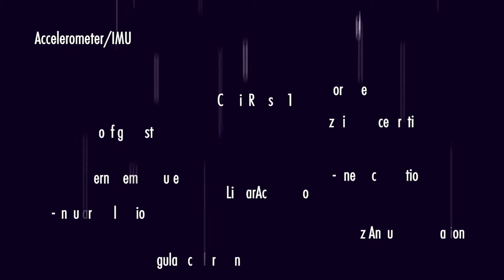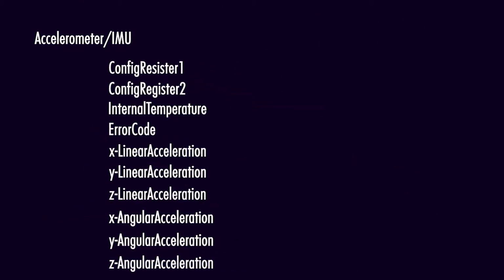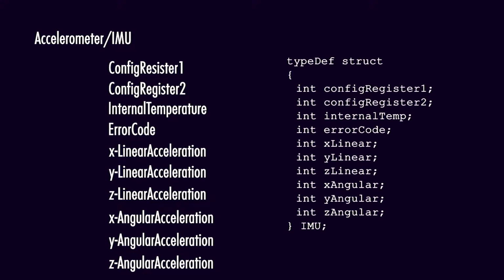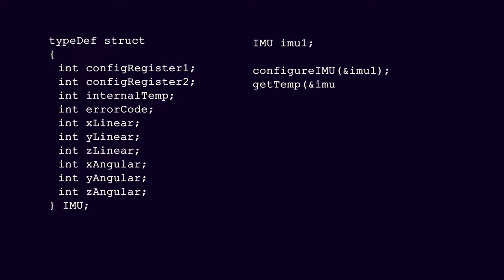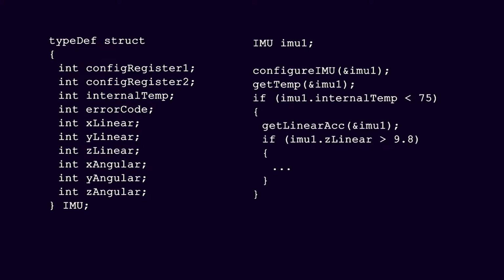It's going to be something that you'll see us do ourselves over and over again in our own code, is to take a logical unit like a timer or a specific peripheral, and you put all the variables that you want, everything that corresponds to the registers and all that sort of stuff, in that structure, and then we can just pass that structure to functions as a whole unit, and it makes the code so much more readable. It's a great way to think about structuring your code.